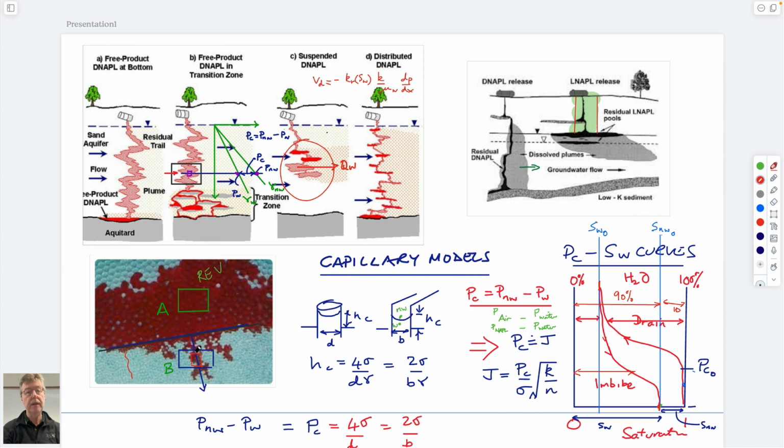Of course, that doesn't really explain why you might have a differential saturation if you take what we've referred to as an REV, representative elemental volume, where you have saturations of the two fluids and they depend on which portions of the porous media they're saturating. And so instead of these simple models which give you the breakthrough pressure, or the bubbling pressure as we've called it, for circular capillaries or for parallel plates, we can do a little experiment that forces a non-aqueous fluid into a wetting fluid already saturating it, and we get a curve that looks like this.